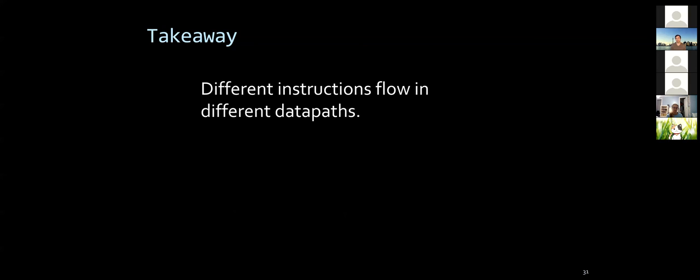We can't technically store a 32-bit constant to represent any address, just because the whole instruction is 32 bits, right? So we have to use different tricks like I'm showing you. When I said one is absolute and one is relative, it's true, but even the long jump, like the J instruction, is still not completely free.